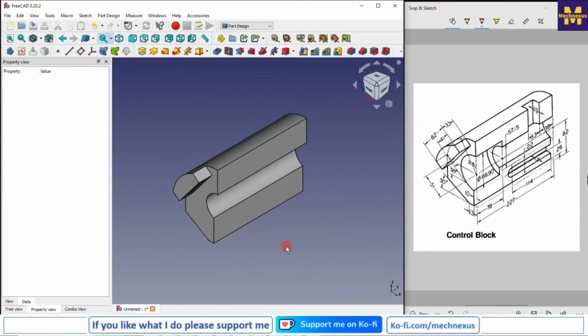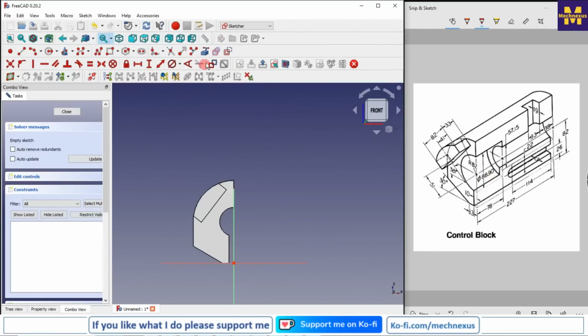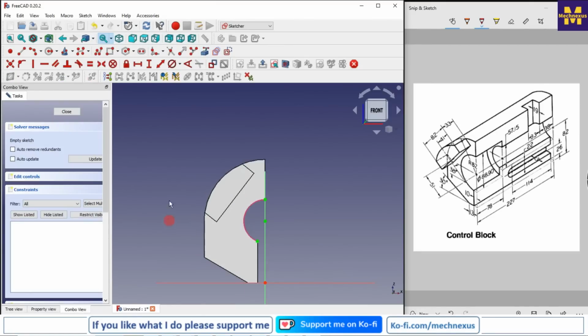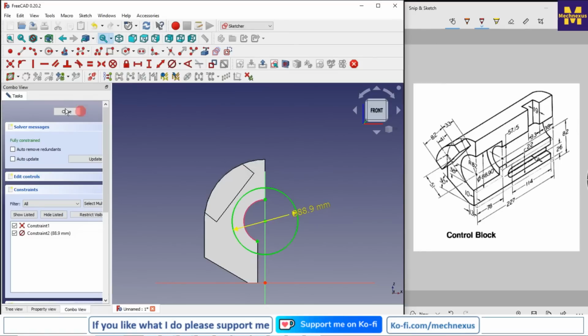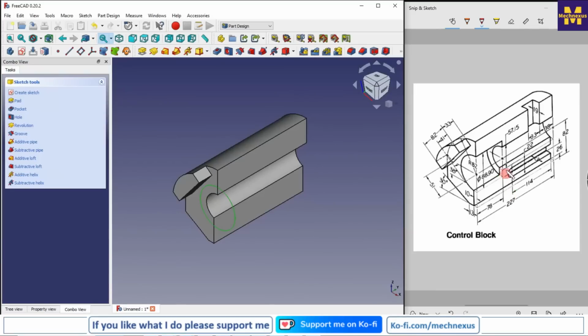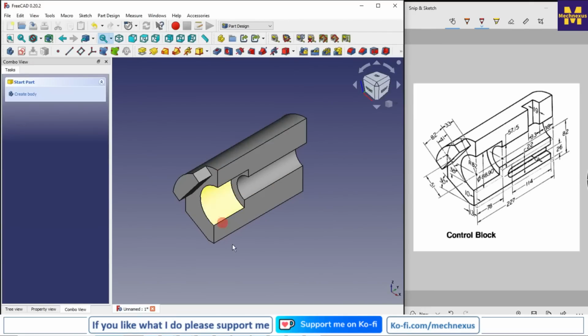Now I will go to the isometric, and now we will create this bore, diameter 88.9. So I will create a sketch and I will project my inner one, select circle and give it diameter 88.9, and I will close it, and this cut is 78, so I will give it 78.